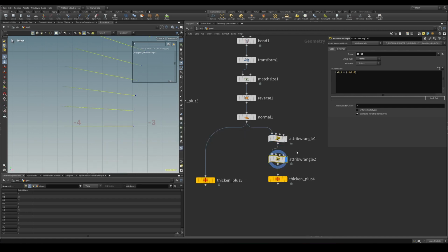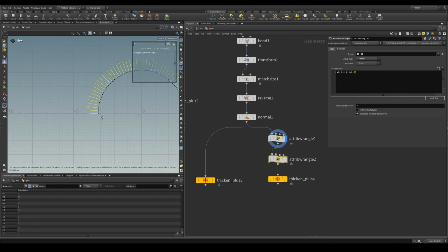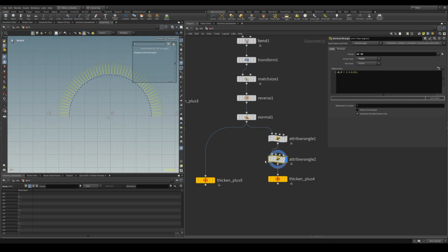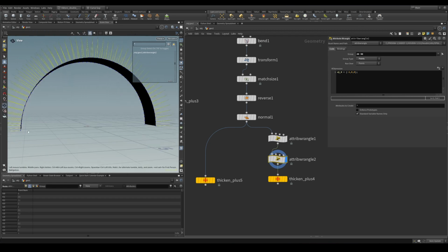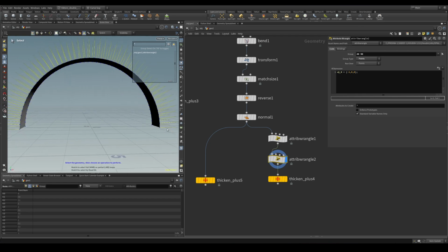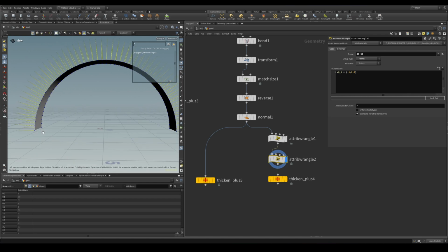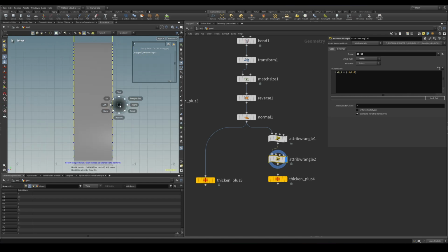You can see I'm taking the start and end points of this arc and flattening them out. For the geometry, there are two points on the positive x-axis and negative x-axis, and I'm just flattening them to align exactly with the grid to be straight.